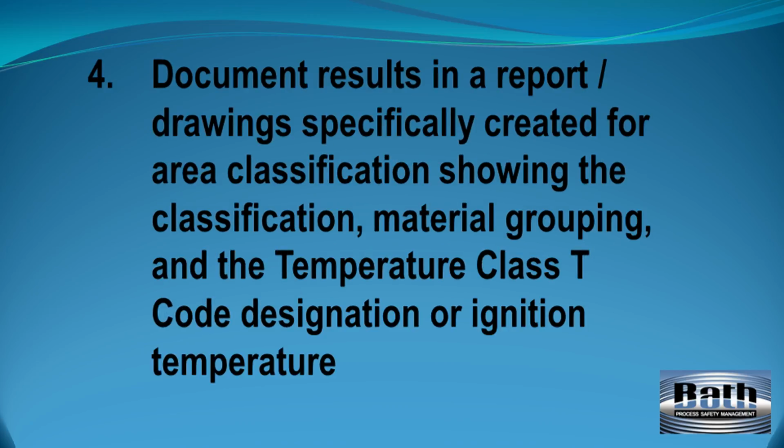4. Document results in a report and on drawings specifically created for area classification showing the classification, material grouping, if applicable, and the temperature class T-code designation or ignition temperature, if applicable.